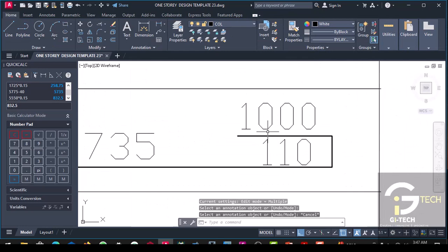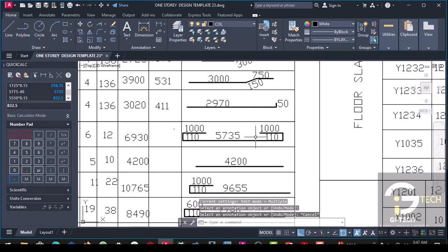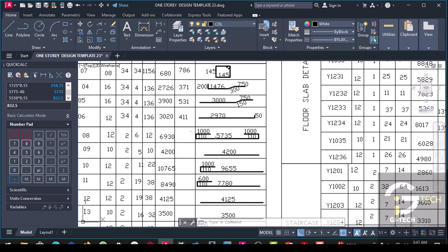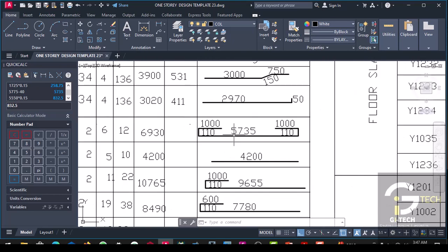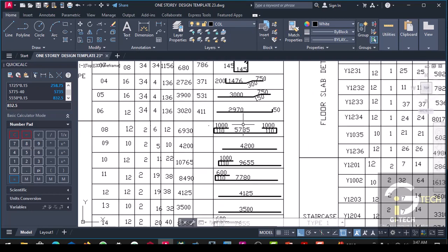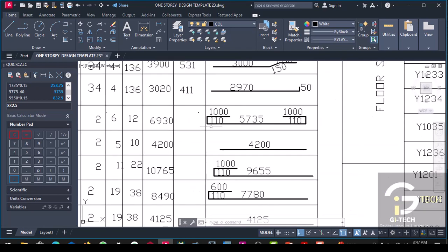Then let 0.15 L be your guide. The length of this returning bar should not be less than 0.15 L for discontinuous edges, and should not also be less than 0.3 L for the interior support.